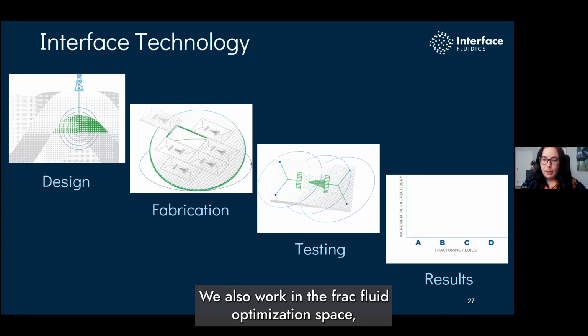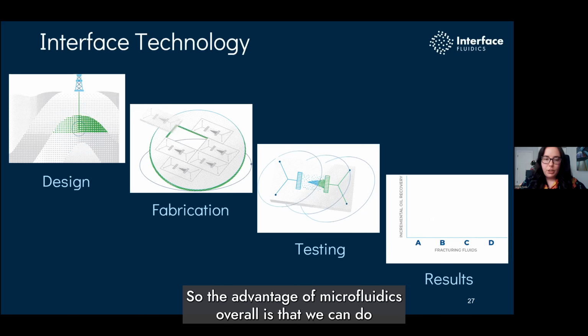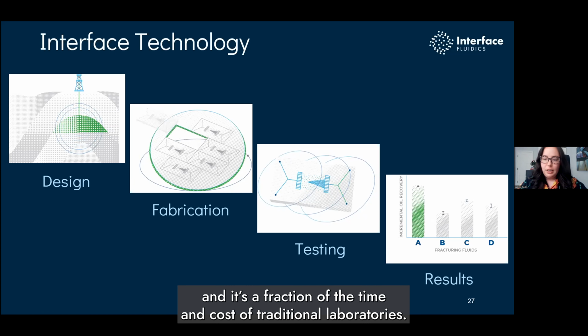All of our tests are conducted at reservoir temperatures and pressures. We're able to go up to 1,000 bar and 200 degrees Celsius. The advantage of microfluidics overall is that we can do a lot of really interesting screening really fast, and it's a fraction of the time and cost of traditional laboratories.